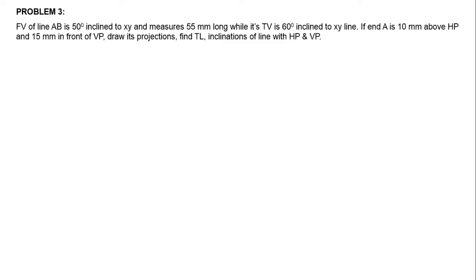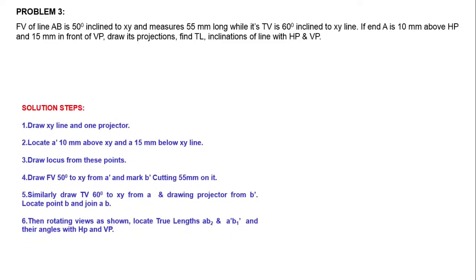This is the second question, and these are the solution steps. First, we have to draw the XY line. Then we can locate the end point A. End point A is 10 mm above HP and 15 mm in front of VP. That means that point lying in first quadrant.